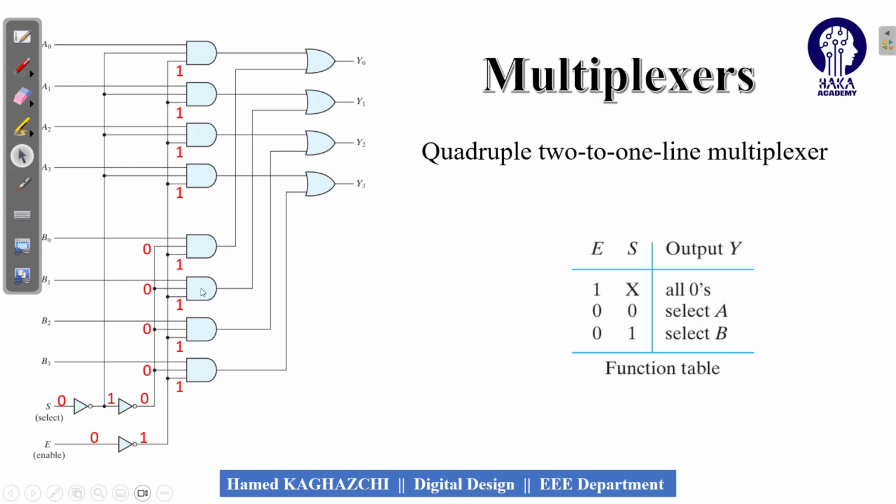And again, because one of the inputs of the AND gate is equal to 0, the output will be equal to 0. And these zeros move to one of the inputs of the OR gate. Now, we have to find the other input of the OR gate. Now, look here. Here will be equal to 1. So it means that all of these inputs of the AND gates here again will be equal to 1, because all of them are connected to this section of the circuit. For each AND gate, we have 1, 1, 1, 1, 1, 1 up to the end.